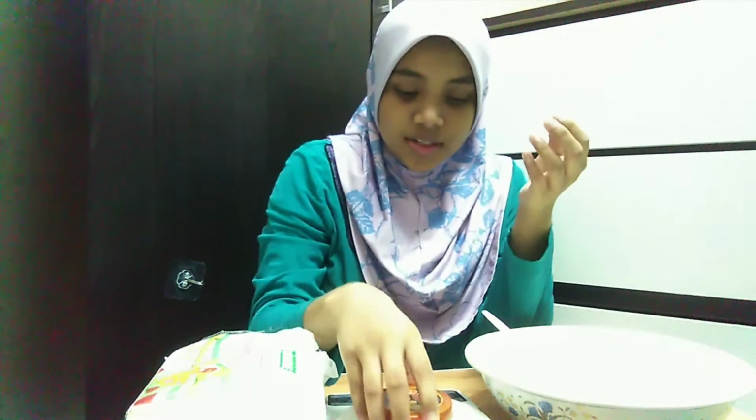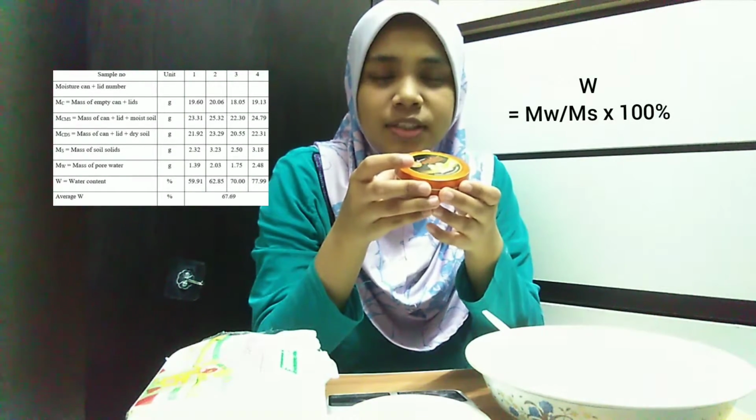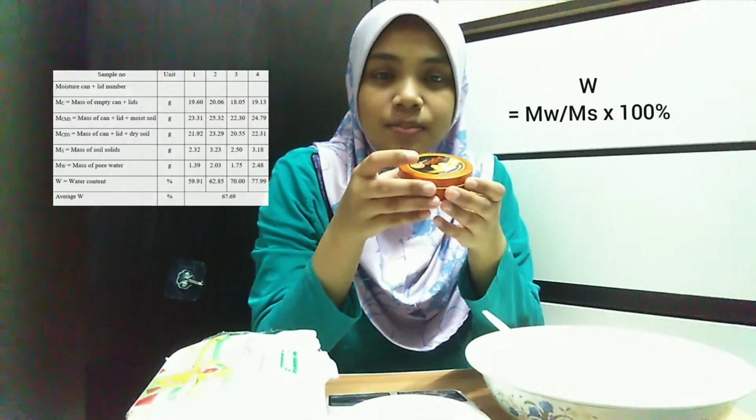After that, we must dry it under the sun. After we dry the soil sample, we take the data again. So, the difference between the mass of soil sample, moisture can and its lid after and before the drying process is the mass of water within the soil sample. To calculate the water content within the soil sample, the mass of water is divided by the mass of solid and multiplied by 100%. The result we get is that the soil sample has 67.79%